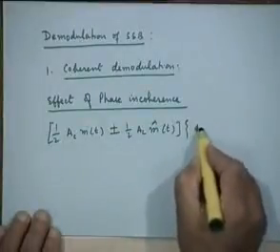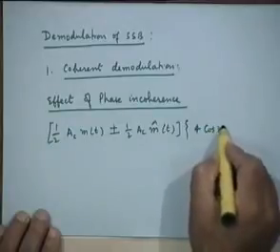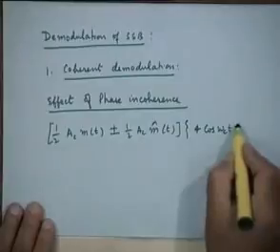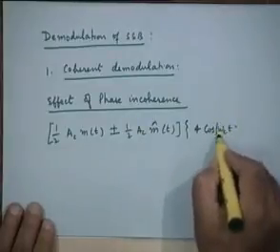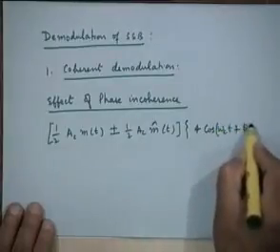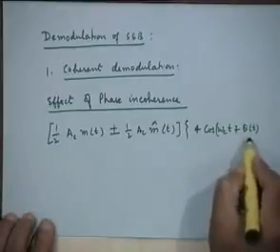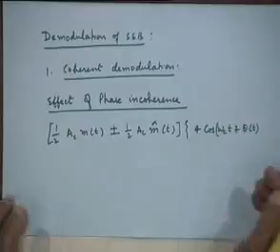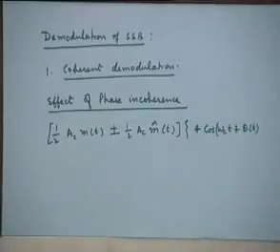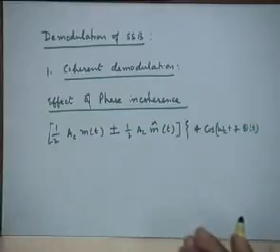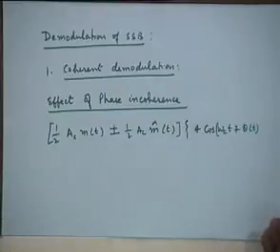For convenience, let's multiply it with 4 cosine omega_c t so that this factor of half and of the trigonometric functions go away. And let's also include a phase offset. In fact, let me consider this as a time varying phase offset, which can model both phase offset as well as frequency offset, right. A frequency offset, for example, is a time varying phase offset.